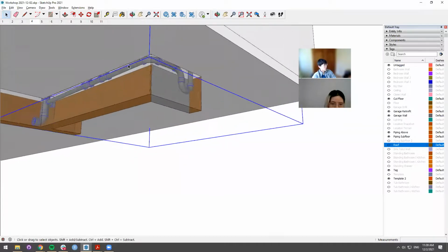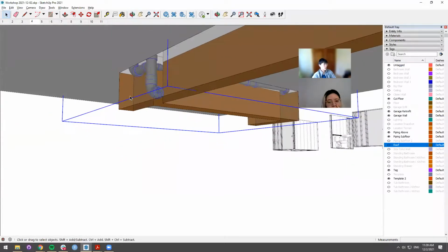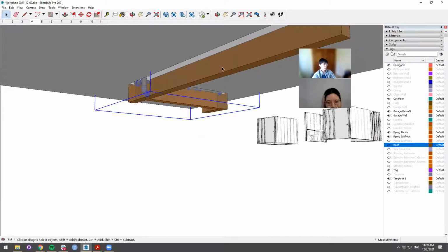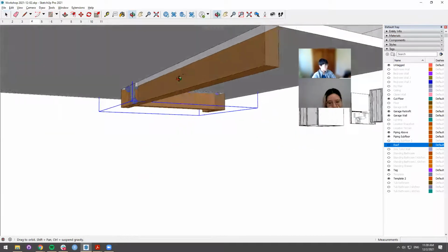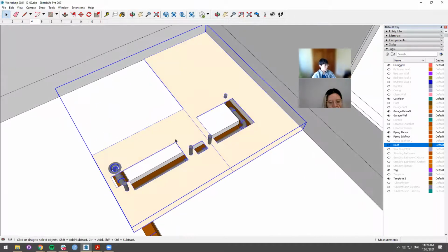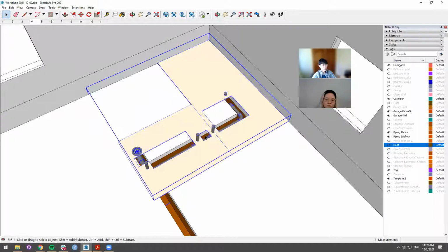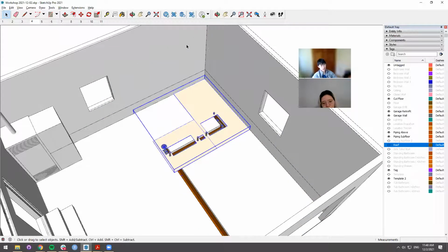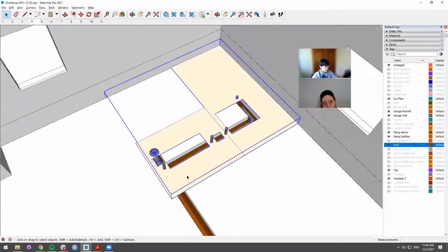So you see a P-trap with the shower, etc. And then this one, just imagine this is a full line all the way to connect with something else in the lateral system. So in this setting, you've identified the exact placement that the subfloor plumbing needs to be at, so that later on, when you bring in the above floor walls and systems, they will be exactly where you need them to be. And again, that's also relative to exactly where the full wall would be placed.